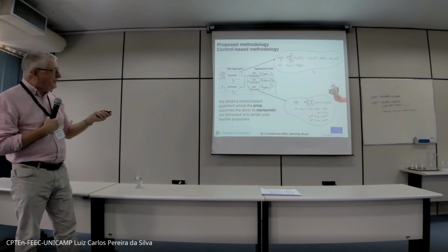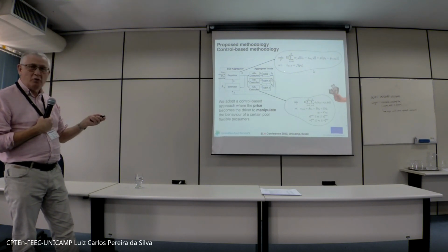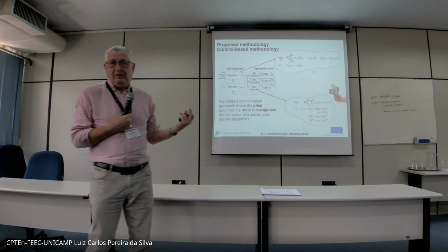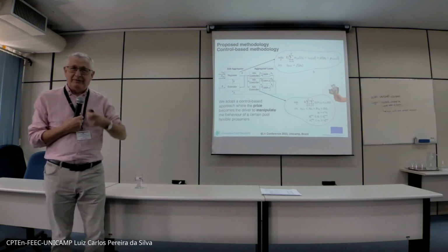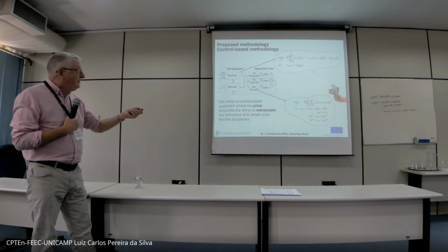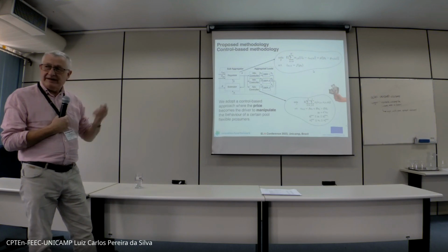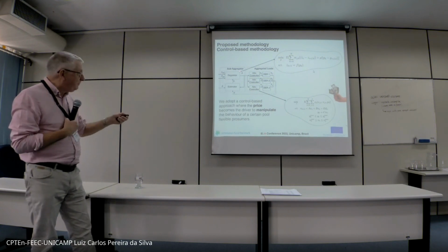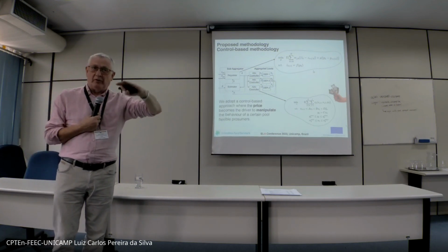This is called a reference-based stochastic controller, and the model here simply links the price to, for instance, the load. Since we have people in the loop, it's not a white box model, of course, because what people are doing is unpredictable. So we need AI, rather black box oriented models, which link the price to the load, and this is the flexibility function. This can be the flexibility function for all the buildings on this feeder. The price is sent to all the buildings to get the response to keep, for instance, the temperature of the transformer station below some level or whatever.